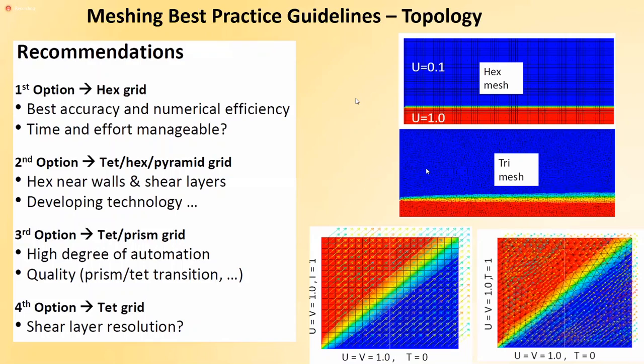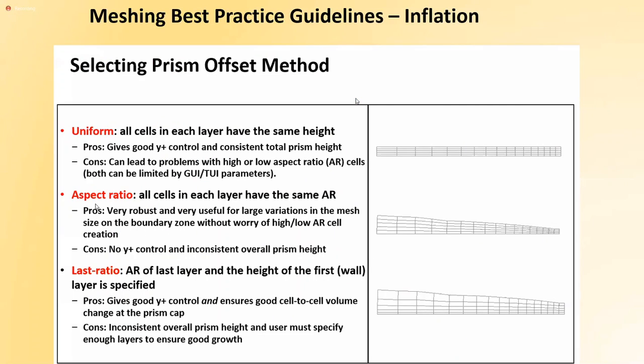This one I've added today. I think many of you don't consider the difference between defining different methodologies of inflation. Every kind of inflation has its own advantages. If the geometry is very sophisticated, you need to connect the boundary layers and stair stepping, and it's hard, and sometimes you can't use a specific one, then you use another one.